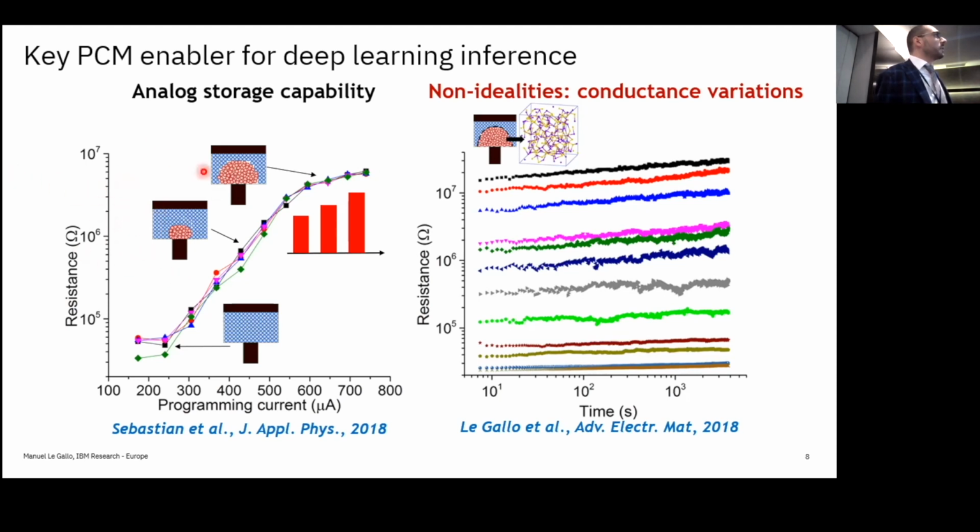And one thing that hinders this is, again, that these devices require relatively high voltages, let's say 2 volts or so. You cannot have just a single transistor to support that, so you usually need more. Also, the programming current is not that small, on the order of 100 microamps or so, so you also need enough transistors to drive this current. So that is maybe the main drawback compared to ReRAM devices.